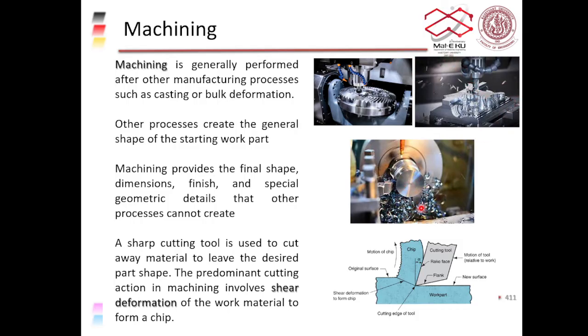But in this case, you can see the chips as well, but the chips are not actually flying away from the surface, but you have strips of chips, right? So you can say that, but which case gives you better machinability? You want small chips that come away from the surface easily, or you want large or long strips of metals on the surface.